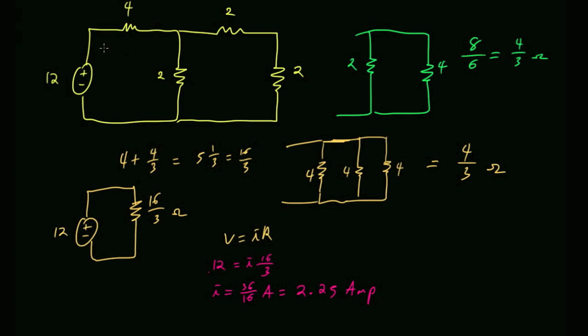So the one thing that we all seem to agree on is if I made that one resistor smaller, my total current was going to increase. And in fact, that did turn out to be the case. So my power supply is 12 volts at 2.25 amps. So now my supplied power is 24 plus 3 is 27 watts.